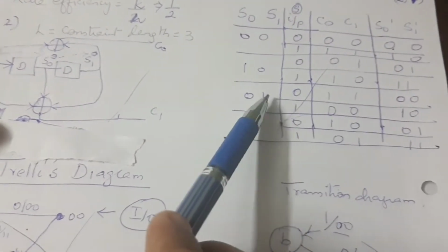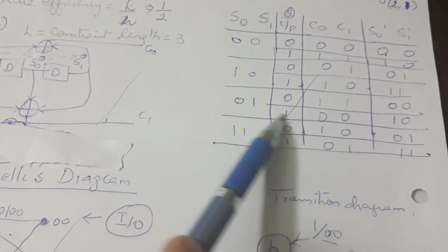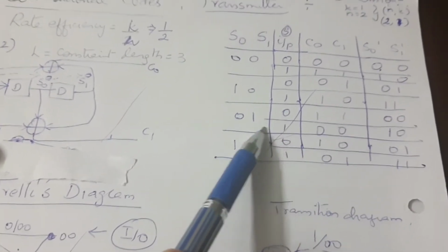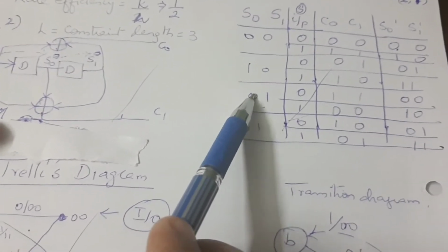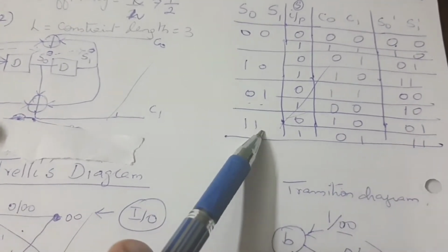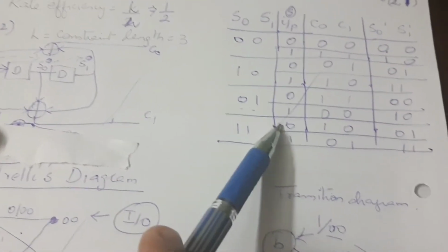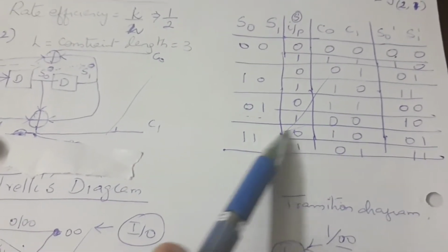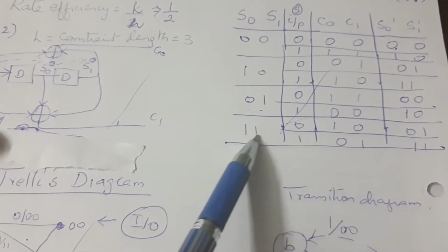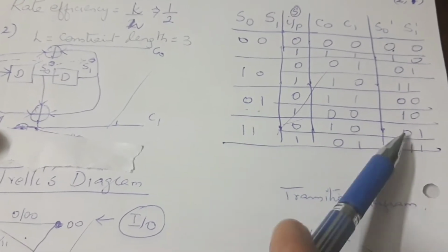Again come for this 1, 1, you will get 0. Again you will have all these 3 conditions added, you will get again 0. To find out your next state, push this input over here. 0 will push to here. Therefore, 1, 0. When you come for your next state, 1, 1. Take the input 1. When you add these two first, you'll get 1. You add all 3, you'll get 0. To find out your next state condition, take this input, come to this level. 1 will be pushed here, 0 will come. Therefore, it is 0, 1.